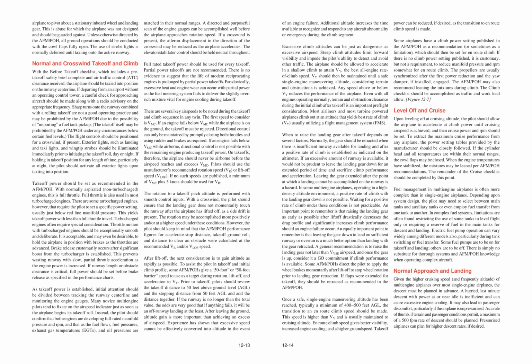Full rated takeoff power should be used for every takeoff. Partial power takeoffs are not recommended. There is no evidence to suggest that the life of modern reciprocating engines is prolonged by partial power takeoffs. Paradoxically, excessive heat and engine wear can occur with partial power, as the fuel metering system fails to deliver the slightly over-rich mixture vital for engine cooling during takeoff.